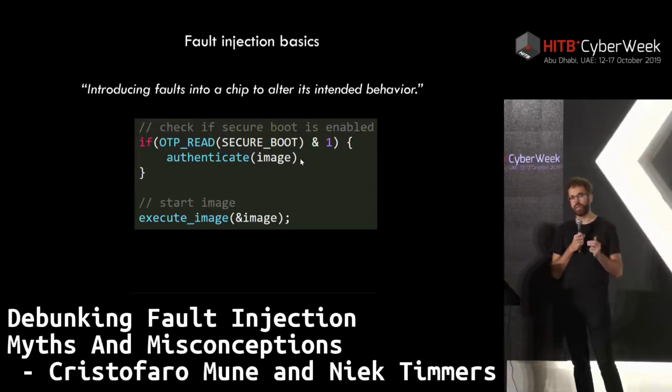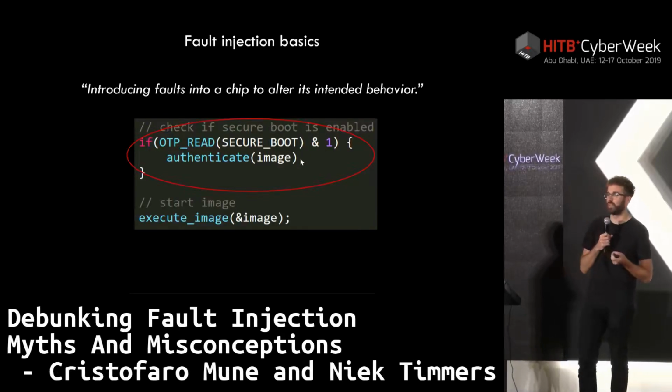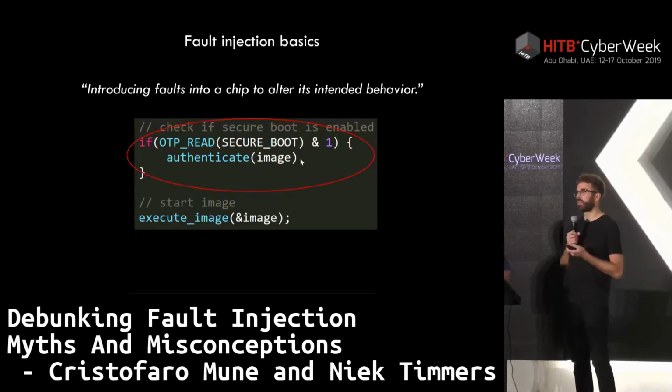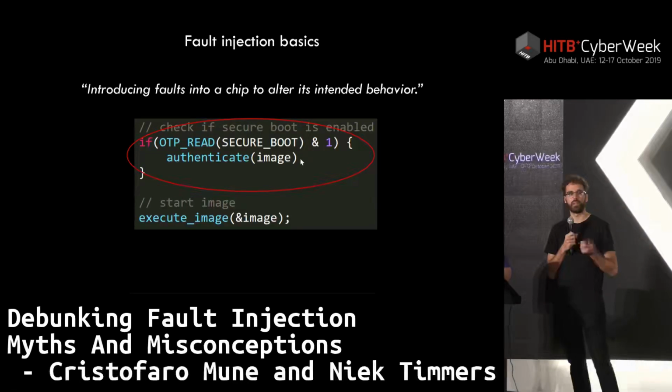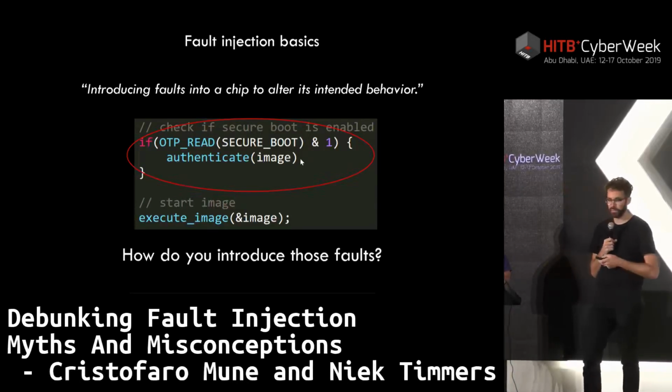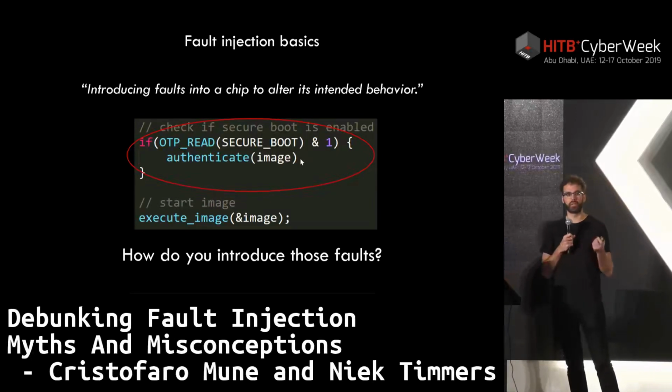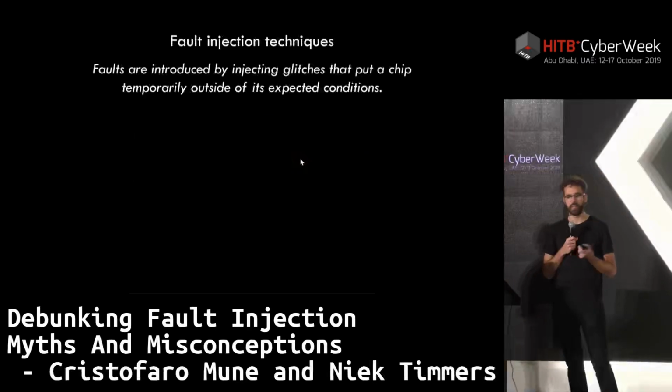You can change the intended behavior of this software in order to bypass the authentication that's being performed. And this allows you to load an image that is unsigned. And this effectively allows you to compromise the device from an early start without actually having any access to the keys that are being used for the authentication. And of course, these faults that you want to introduce, they need to be injected somehow. And that can be done in various ways.